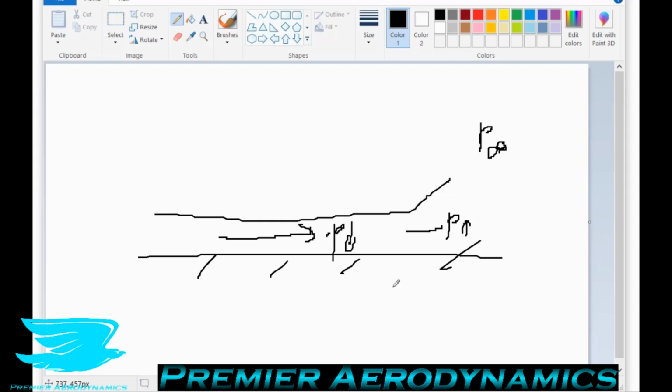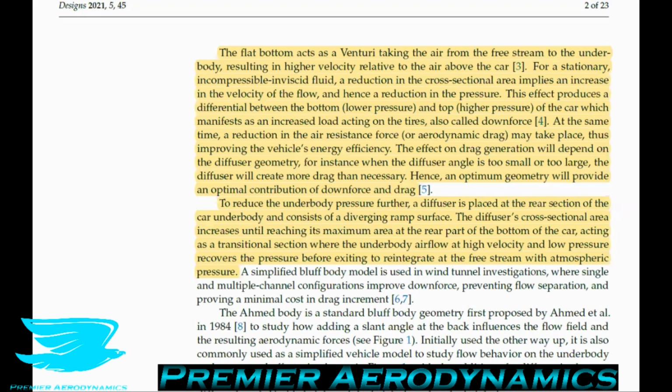What this does is it changes the efficiency of the diffuser or the outlet or whatever you're using. So the ideal case is when you have perfectly expanded flow, which means that the pressure coming out equals the pressure from the atmosphere. If you don't get that, you'll either get the atmospheric pressure pushing back into the diffuser, or you have not used all the energy you could from the flow otherwise. So there are two different cases which are suboptimal. The optimal case is when the pressure coming out equals the atmospheric pressure. So that's what they talk about here.